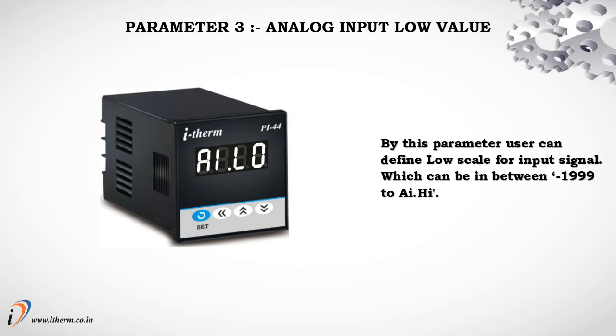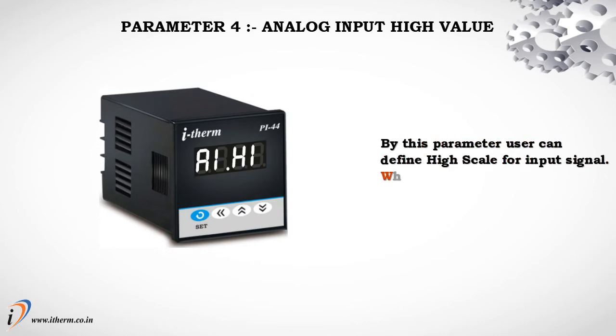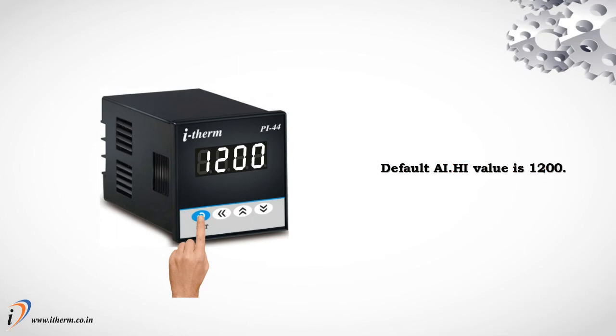Parameter 3, analog input low value. By this parameter, user can define low scale for input signal, which can be in between -1999 to analog input high. Default analog input low value is 0. Parameter 4, analog input high value. By this parameter, user can define high scale for input signal, which can be in between analog input low to 9999. Default analog input high value is 1200.